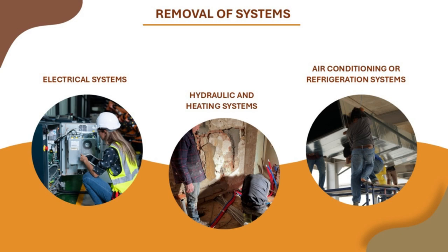Air conditioning or refrigeration systems. Recover refrigerant gases following current regulations, e.g. F-gas regulation, using certified equipment. Safely remove internal and external units, paying attention to anchoring systems.